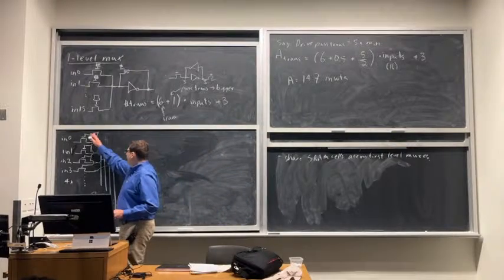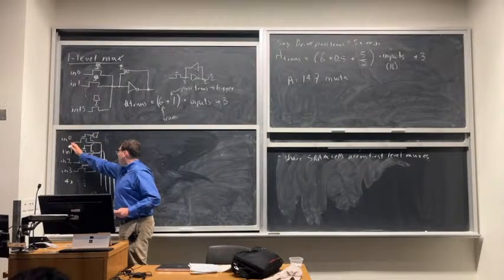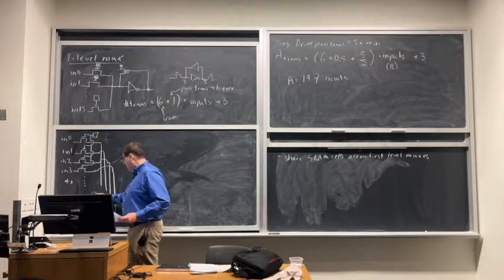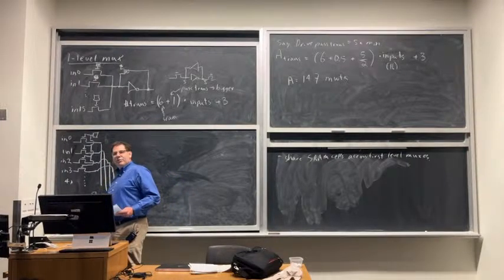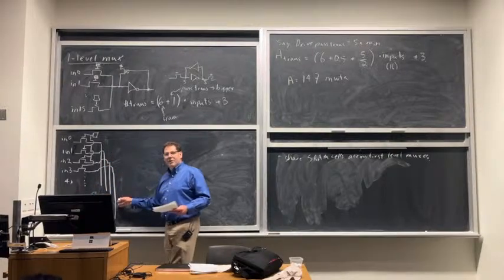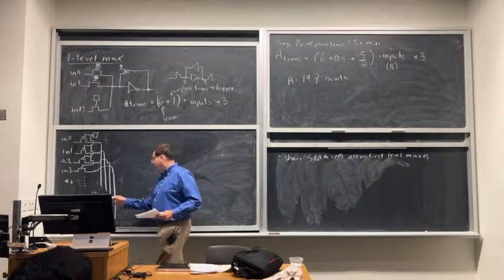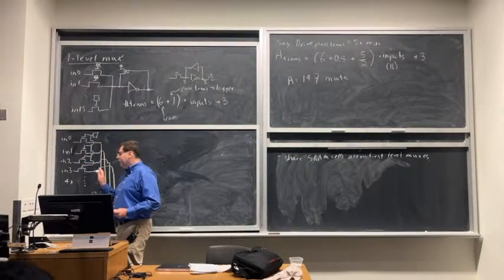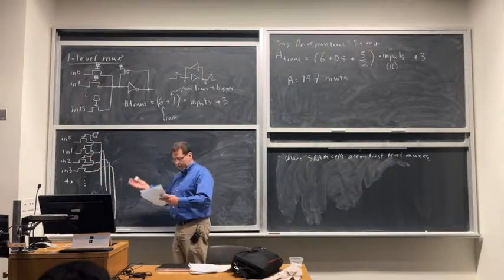So if I turn on this SRAM cell, these 4 inputs get copied onto these output wires. If I turn on this bottom SRAM cell, the last 4 inputs, so input 12, 13, 14, 15, get copied onto these 4 wires, and so on. Okay, so depending on what I set, I copy a group of 4 signals onto these 4 intermediate values.